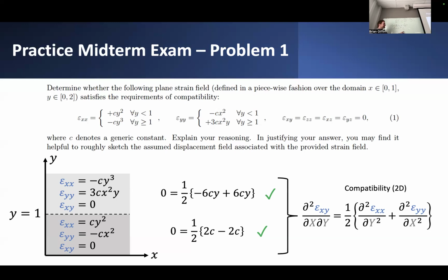such that we will always satisfy this condition. So if we're trying to make this comparison by just looking at the y displacement without any additional information, there's no way to actually verify whether this is going to result in a compatible y displacement field. It depends on our boundary conditions, how we define them, and whether or not it results in some kind of value for this extra term f on the plus and bottom sides. Maybe it will, maybe it won't, but we can't say definitively. We could pick it such that we do always satisfy it.